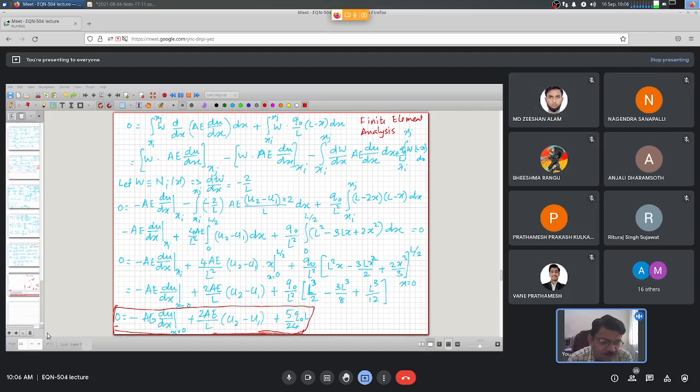And even for this small problem, you will find that it very soon becomes very difficult to handle manually. If you use a quadratic element, you will find that without computer tools for solution of simultaneous equations, you cannot handle that. So finite element method in general cannot be implemented without assistance from computers, but even computers have their limitations. They are finite machines, so their capacity is limited. So very delicate balance is required between desired accuracy and what is practically feasible based on the kind of computer system you have at your disposal.